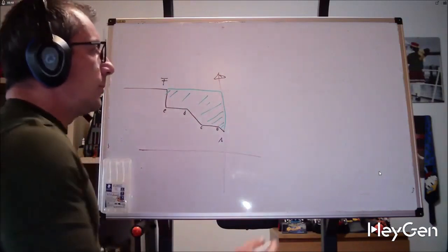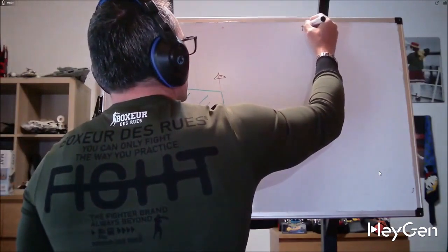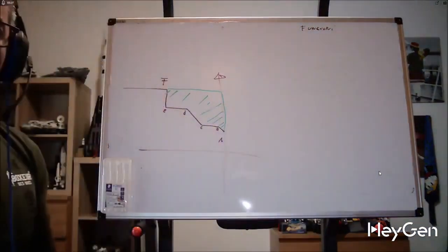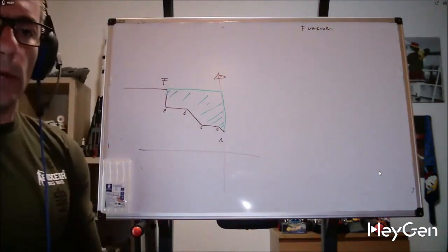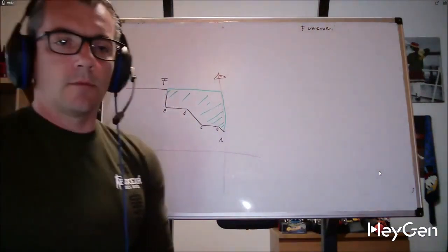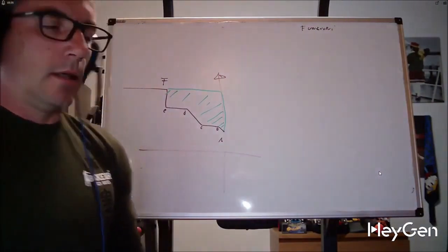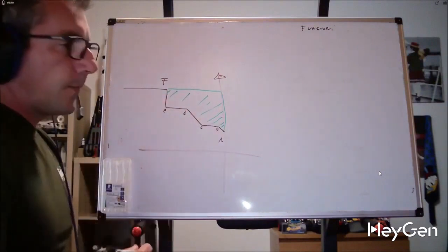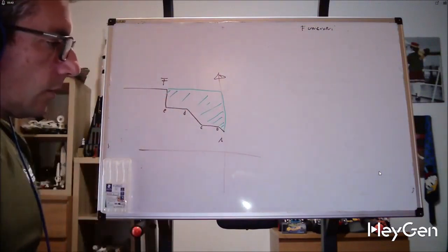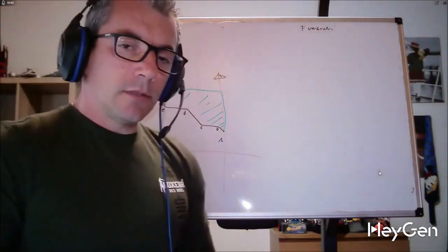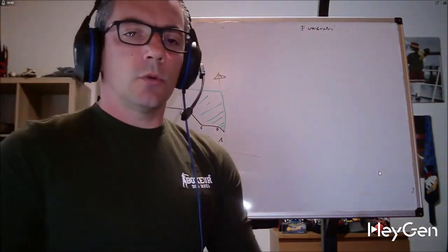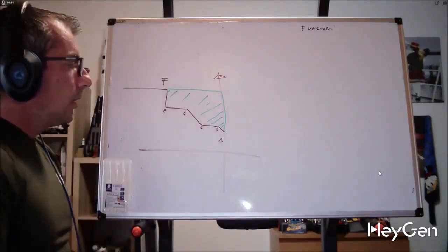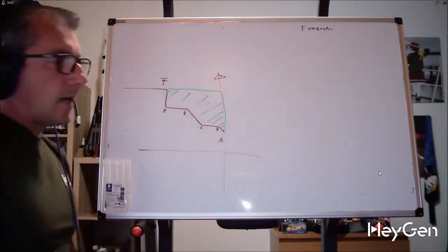Let's try to understand a couple of concepts first. We're going to put the various preparatory functions into our program. What are the preparatory functions? We've already mentioned M4, spindle rotation, tool change, turret rotation, speed limitations, and so on. After that, we need to think about this profile. So, what does the macro ask us? It asks us for information. Why am I telling you all this? Because whether you're working on one CNC or another, the information you need to provide is pretty much the same.